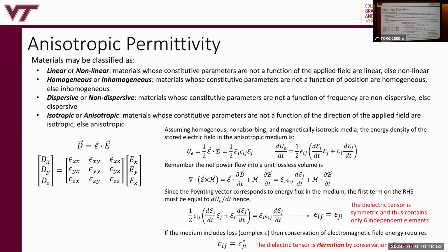You need current to oscillate in the direction of the polarization that you want. So you need some kind of vertical strip of conductive material, for example, if I want vertical polarization. And if I don't want to excite any of the other polarization, then I want this to be thin. If I want both polarizations, maybe dual LP, then I can make a horizontal or diagonally directed metallic strip. And if you describe this diagonal metallic strip into its X and Y components, if I come in vertically, it responds. If I come in horizontally, it responds, right?